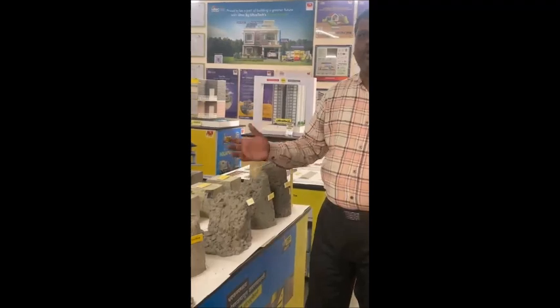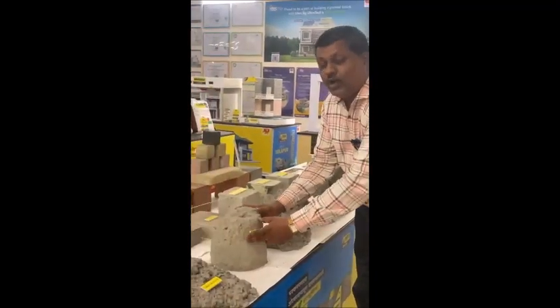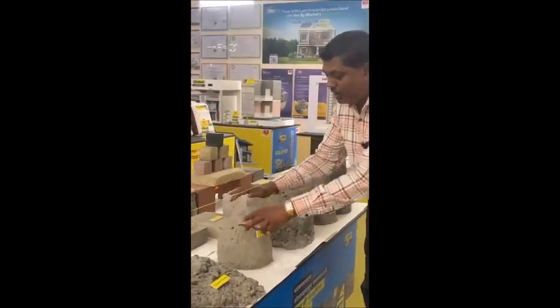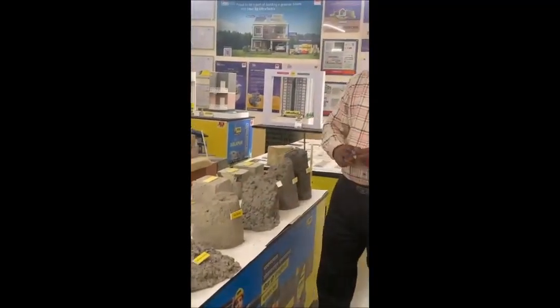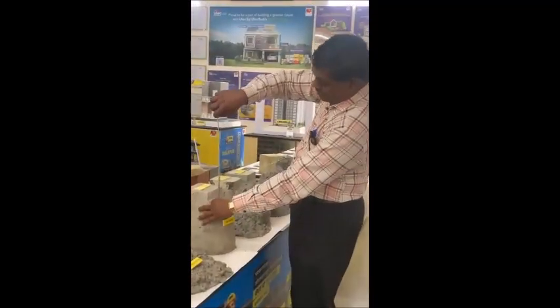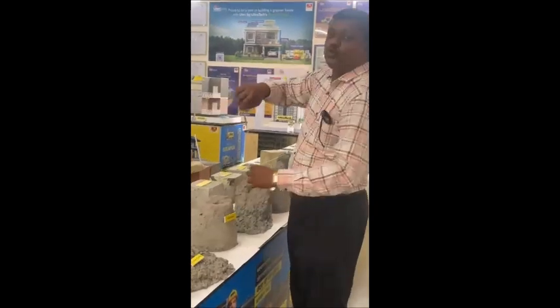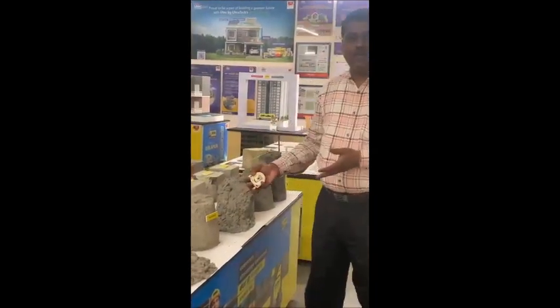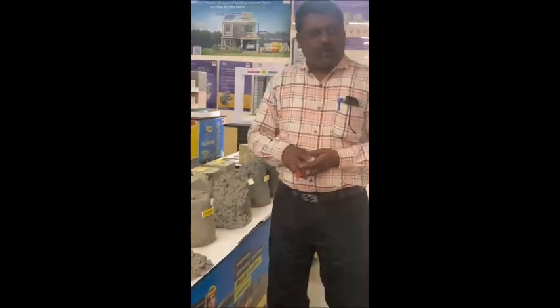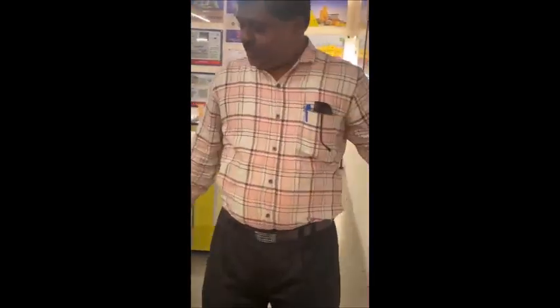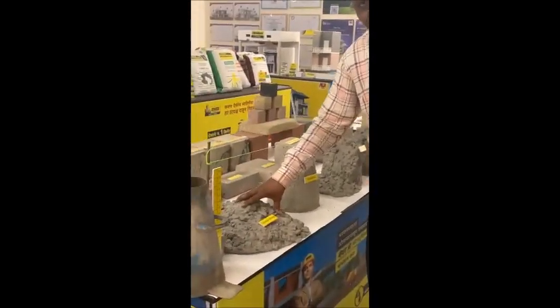Now, the true slump, according to the nature, is the type of nature which is expected. All around the slump, the concrete subsides evenly, and the value of this slump is about 110. So a true slump of 110 is useful for our RCC work. Now, if you go for the last type of concrete, this nature of concrete is a collapse slump.